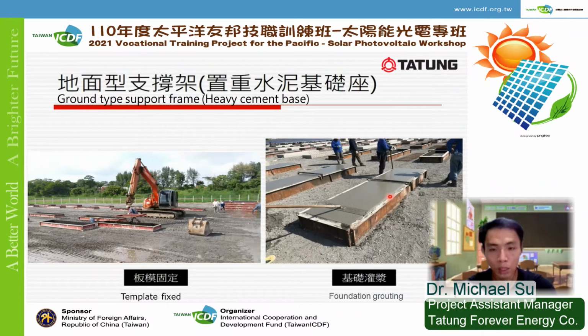Now, besides piling, we can also use big blocks of concrete to lay the foundation. We can use this method when we can't pile. Maybe the ground used to be a landfill and the structure is not stable enough to withstand the piling, or the piling may accidentally penetrate the protection layer below. It will contaminate the surrounding environment. So in these cases, we will choose to use these big concrete blocks instead.